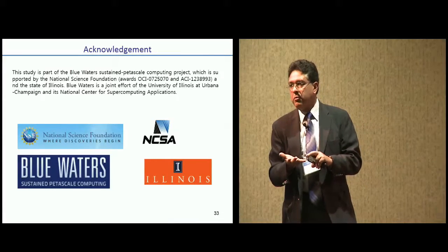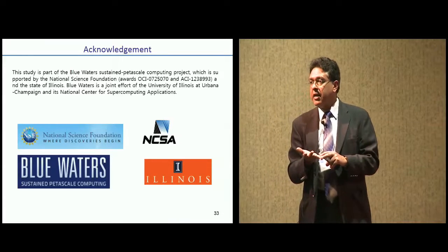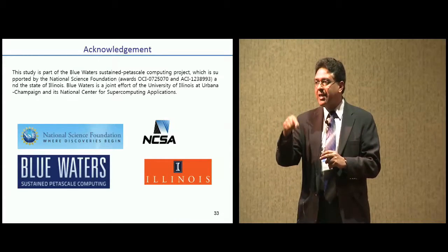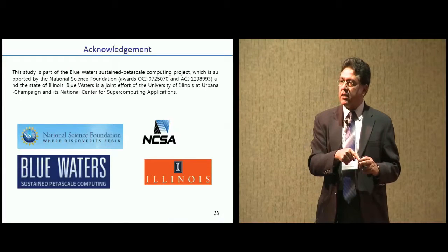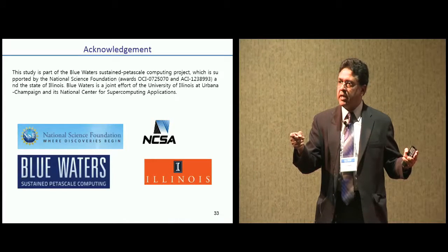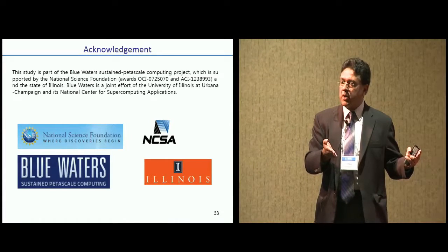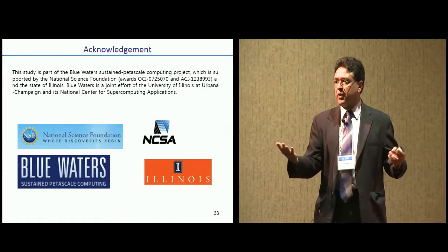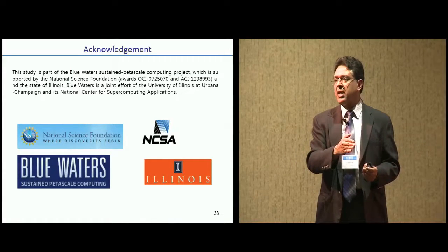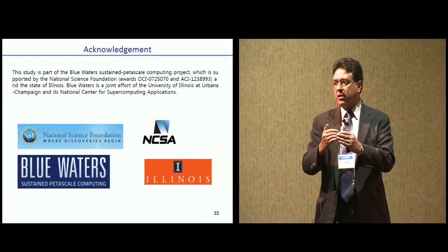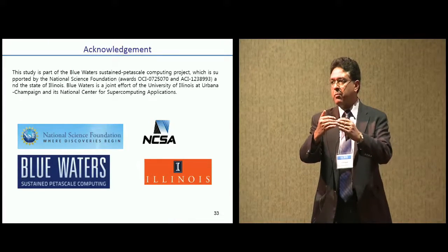But what does it mean? It means that your flow models are more complicated. Your flow structure interaction can bring in some instabilities. And that is where I was saying that we need implicit methods, because implicit methods try to solve the system of equations at every step, whereas if you're using explicit methods, they are only projecting from step n to n plus 1, n plus 1 to n plus 2.